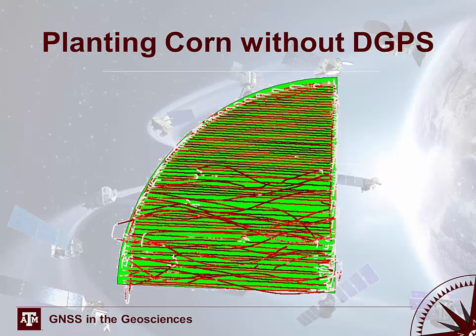It's also used in precision agriculture. Precision agriculture, for those of you who are not aware, is an incredibly lucrative business. It's continually increasing. It's a multi-million-dollar industry that's continuing to grow and will continue to grow. DGPS is used in precision ag systems by enabling the farmer to more efficiently use the land. So here you can see a field, and say the red line running throughout here is where the equipment ran. On the top is part of a field mapped with differential GPS. Conversely, on the bottom you can see the rows are all over the place. This is a case where they attempted to use GPS. However, they didn't have that differential GPS. They didn't have that high degree of accuracy and precision. So it's really important in precision ag to use differential GPS systems. And I'll talk about this in the next lecture a little bit more specifically, how those systems work and what are some of the advantages or disadvantages to this application.